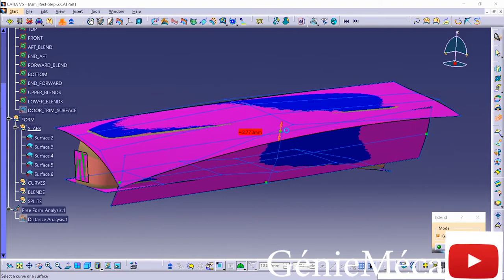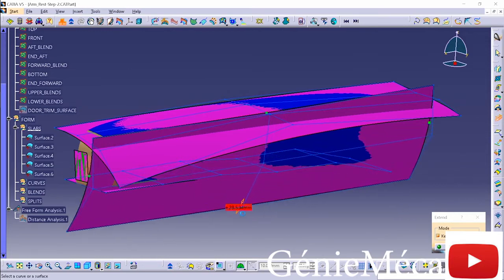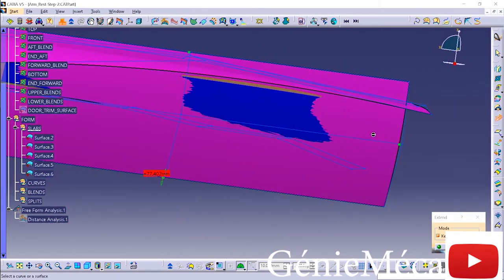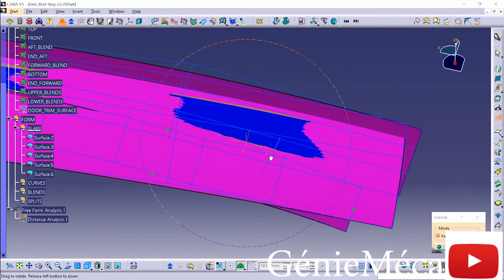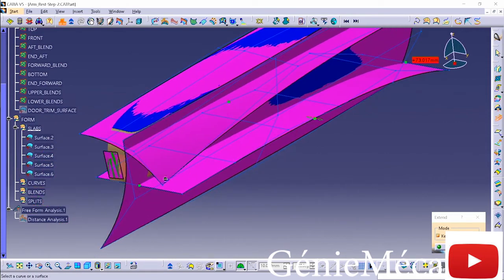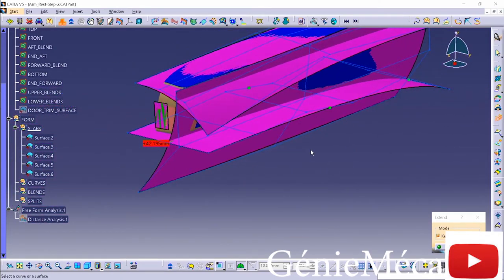Enlarge that. Bring this up. And drag this down. There we go. Again, making sure that it completely encompasses that part. If I don't, I can always go back and extend it again. And just work my way around the part. You can see as I'm pulling things, the control points recompile themselves in order to maintain the initial position of that first surface. So there's no deviation really that's going to happen back to the mesh as measured.